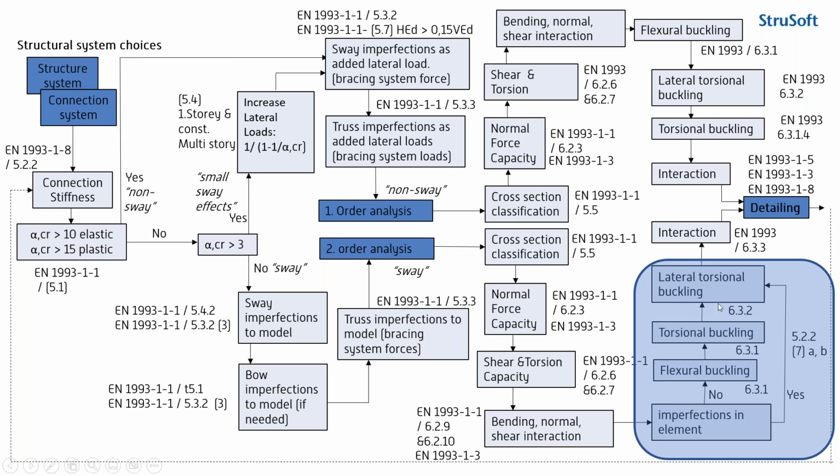So like the first dialogue, I show you that there's a question of how you handle your design process in FEM-Design. You have to select whether we should include the second order effects of design of element or not. And this is Eurocode chapter 5.2.2 sub 7 a and b.